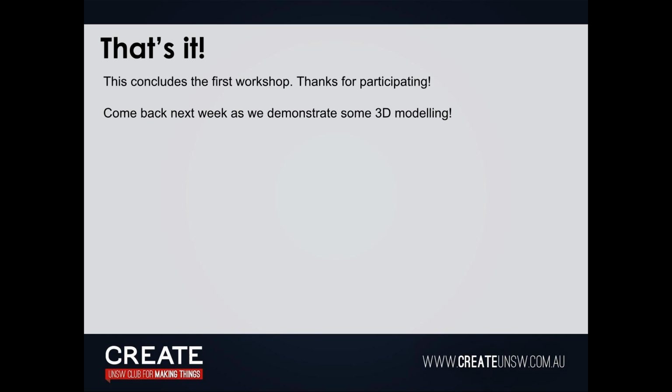So let's go back to the finger part, right? How do you enter a sketch on that face? Oh, so middle mouse button. Whenever we're using Fusion, it does help to have a mouse. I wouldn't say trackpad, but a mouse is pretty much what you want.